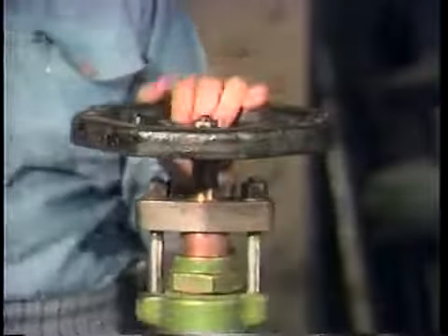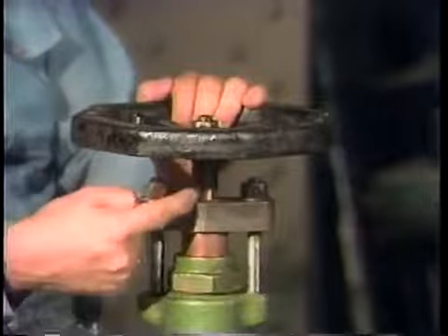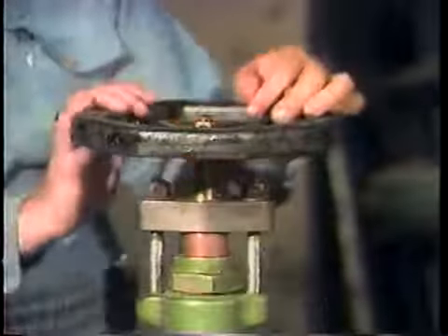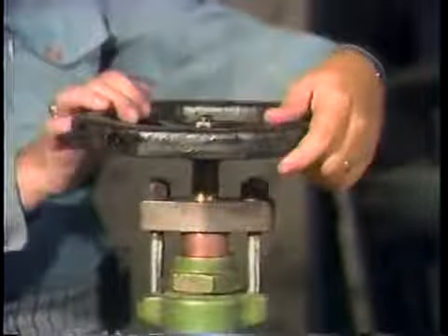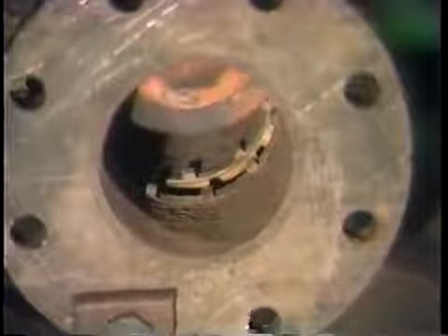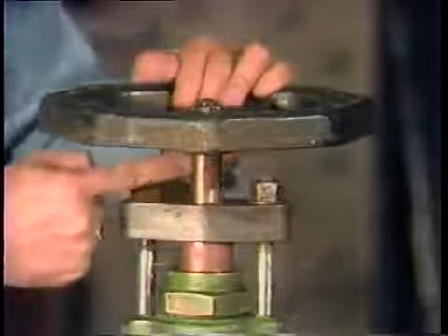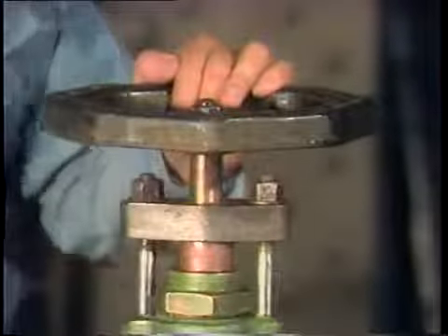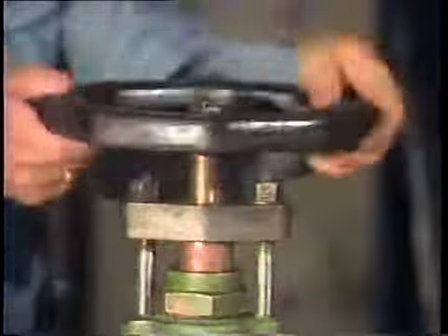Another common type of stem that you'll find on gate valves is the non-rising stem. Now, this is especially useful where space is limited. On these valves, the stem is bolted or keyed to the hand wheel so they rotate together. The disc is threaded to the stem and threads itself up the stem as the hand wheel is rotated. Notice that there are no threads here on the stem. Now, this keeps the stem from rising when the hand wheel is rotated. The non-rising stem valve is well suited for mechanical operation since the stem will not get in the way of an electric or hydraulic motor.